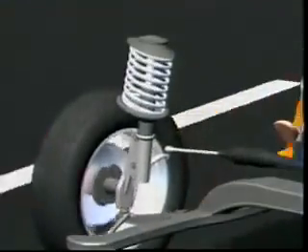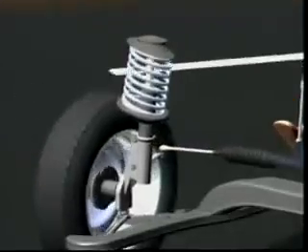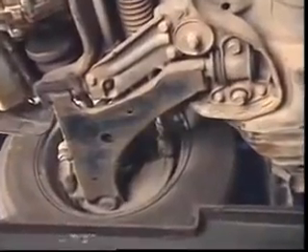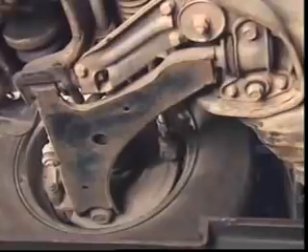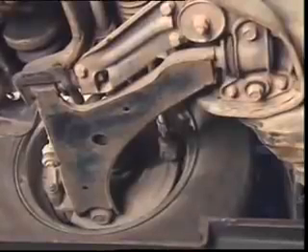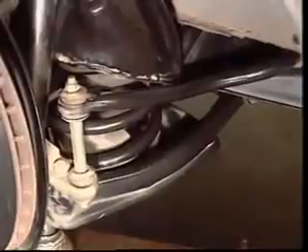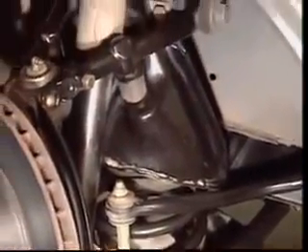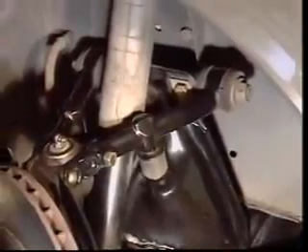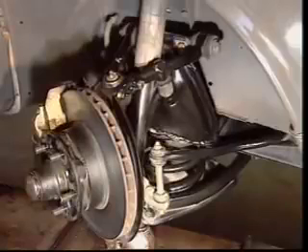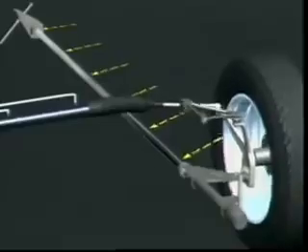This maintains the location of the control arm during braking and accelerating. In this front-wheel drive suspension, the control arm is a wishbone shape with two widely spaced mounting points. This prevents backward and forward movement, so a tension rod is not needed. Wishbones can also be used in a parallel link system. They can be used in pairs with the coil spring between the lower wishbone and the suspension crossmember. Alternatively, the upper link may be a wishbone with a coil spring mounted above, combined with a single pivot lower link located by a tension rod.